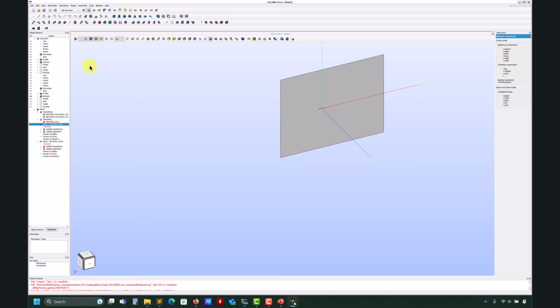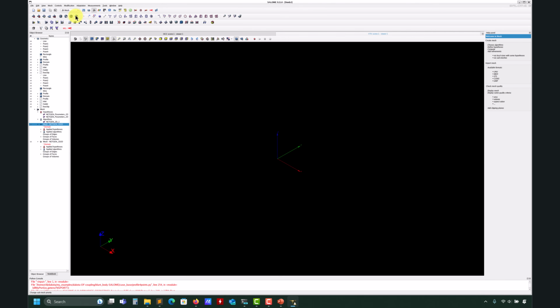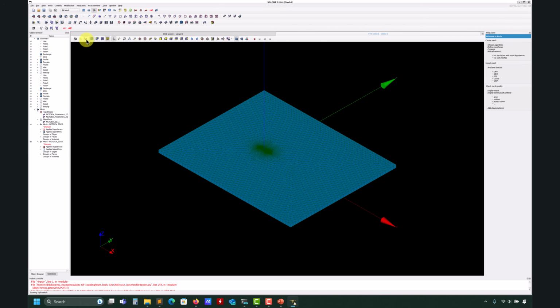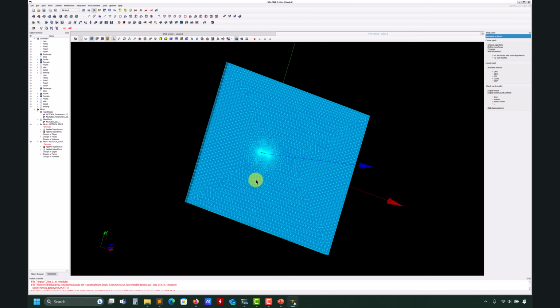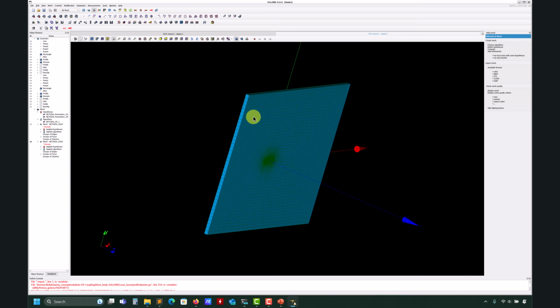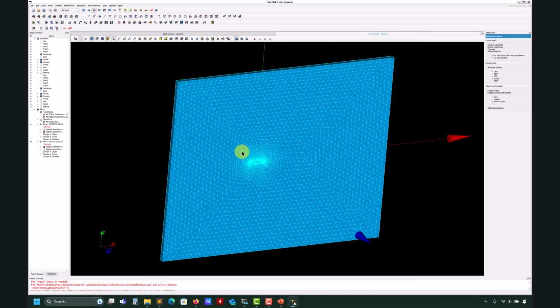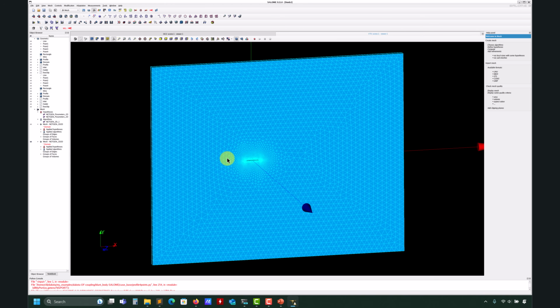It works very well for boundary layers, so you don't have any more the problem that is snappy, which is not a problem if you know how to use snappy, you can control that. And now if I move here to the meshing tab, see that you have your mesh there. And here we do an extrusion. Remember that in OpenFOAM you need to have that extrusion, so we can do it here. And there you go, you have that mesh.